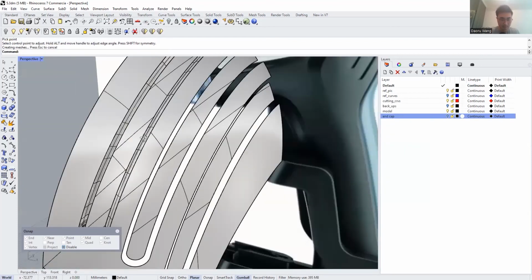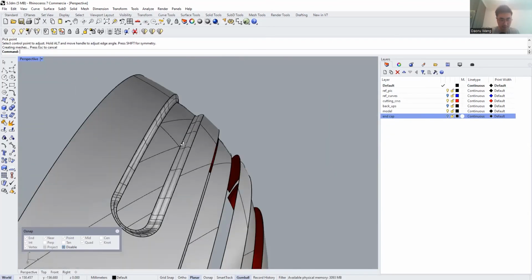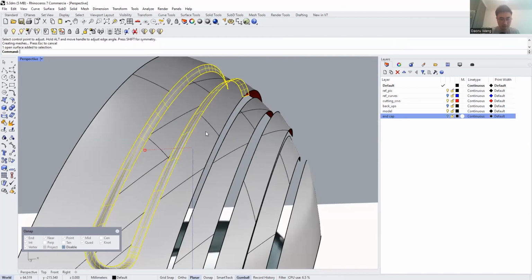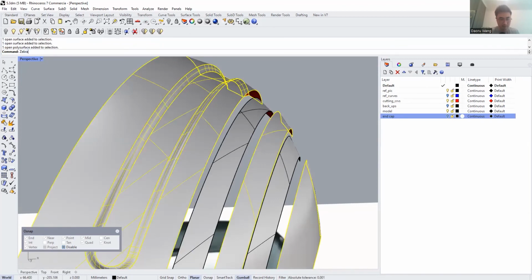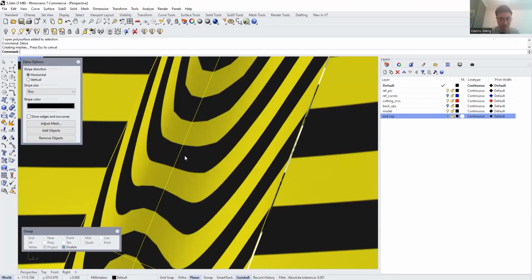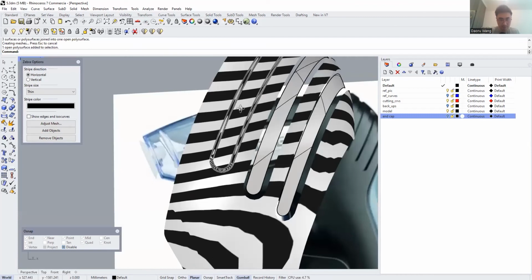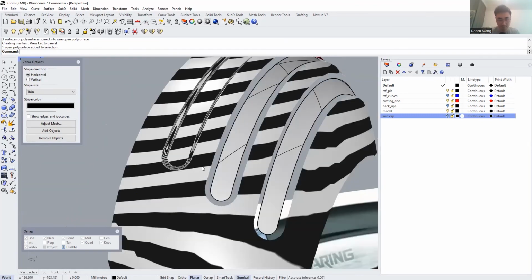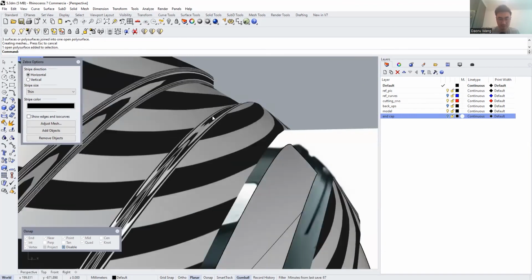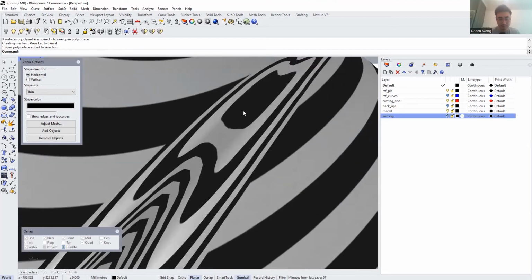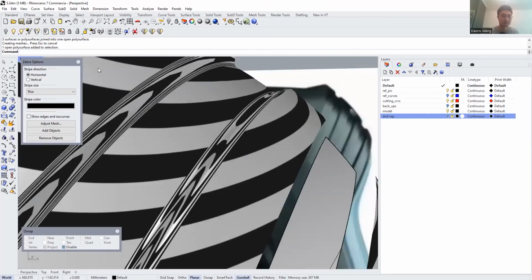And you can see that this is much better. The transition is smoother. And we will do the zebra. Bang. Right. There's this gap in between, but it's actually just the algorithm's way of calculating. If you join them together, you see immediately it disappears. So this is perfectly G3 continuity in between, which is even higher than most of the industry standards.